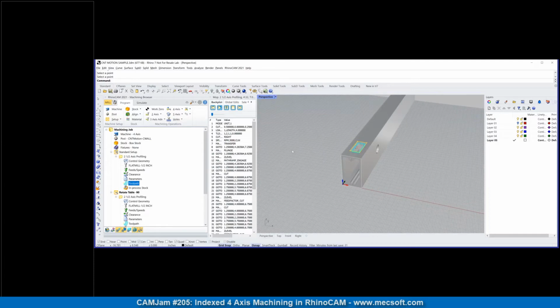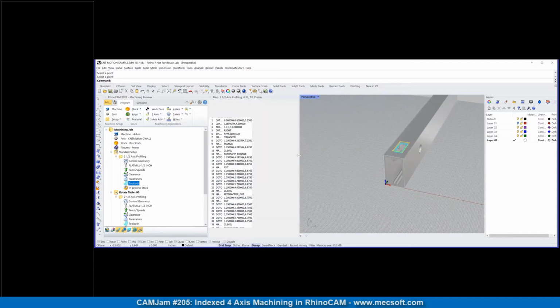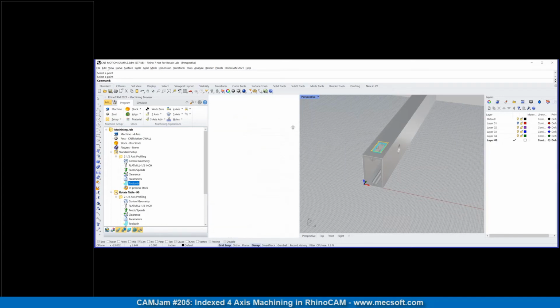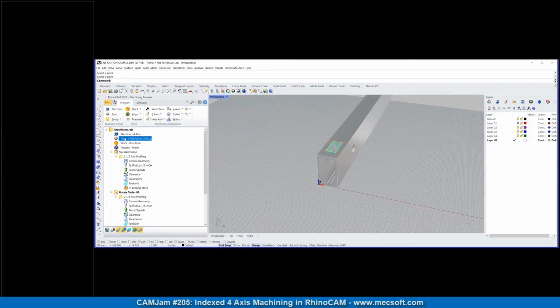You can see the posted geometry, posted coordinates. So these are all the different go-to motions and things of that sort. In a rotation, everything is already figured out for you when you do the posting. So yeah, you had a question there, Philip. What does that do? You asked me. So basically that's once you get that file, that's what you send to the machine tool, right? I see that now after you showed me the list. That little pop-up list of it. I saw that. Yeah, and you take that to the CNC controller and then load that and run it.